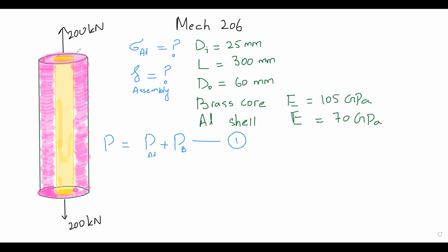All of you can ask, are you applying the load on the brass or on the aluminium? No. I will again read the wording. It says by means of rigid end plates. So you can assume that you have put a little disc at each end. You have kind of glued that disc. So at the end of the day, when you are putting a load, that load is transferred to aluminium and brass. Got it? Okay.